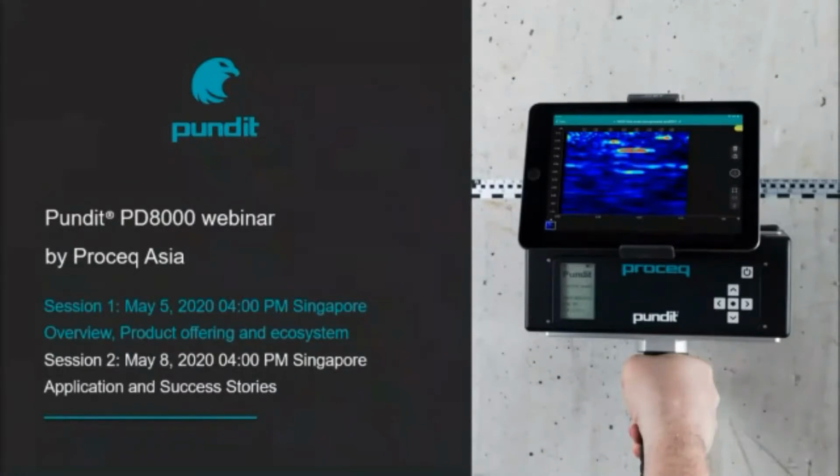One last question. Can we detect hairline cracks? You can detect it if it's more or less parallel to the surface. That's what we call a delamination. It doesn't matter how thick it is. So even if it's a hairline crack, we detect it, we get a total reflection.